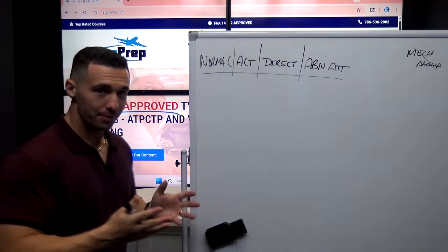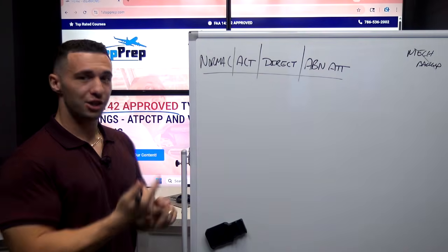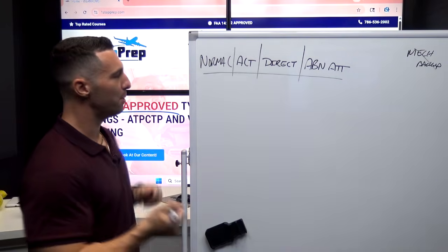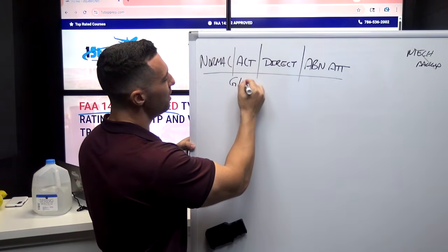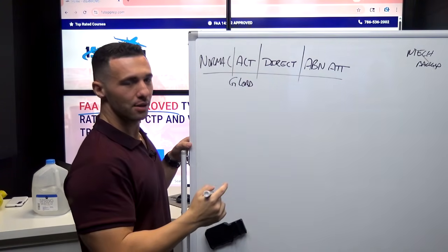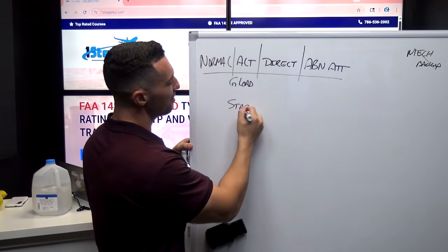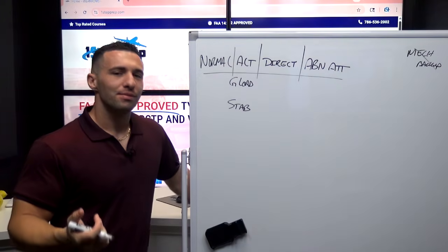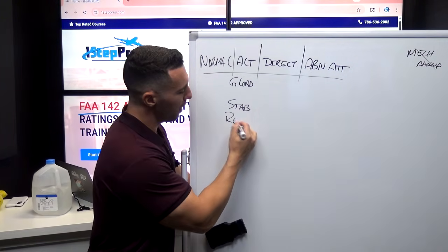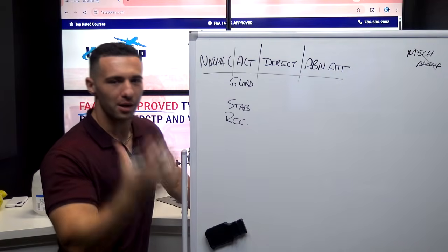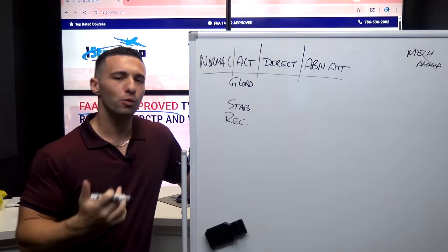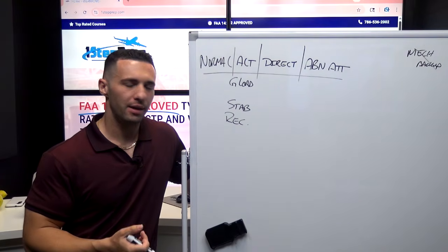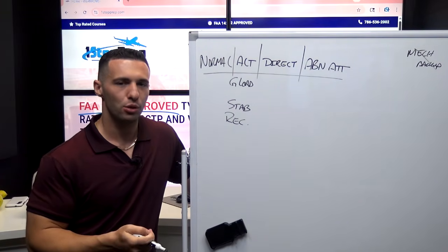what do we have as far as protections? Well, we got G-load protection, and that's really about it. And then you have stabilities, something called stabilities. So I'm just going to list here, we have G-load protection, and then we have something called stabilities. Now, stabilities are not protections. Stabilities are recommendations. Why do I emphasize they're recommendations? Because they can be overridden. I can override a stability. I cannot override a protection, but I can very much override a stability.